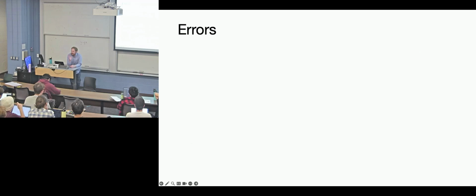What can we say about the least significant bit in error? The least significant bit is bad. So you use the quantization error, and you can just say however many bits that's worth, just knock it off, and then whatever's left is what you care about.